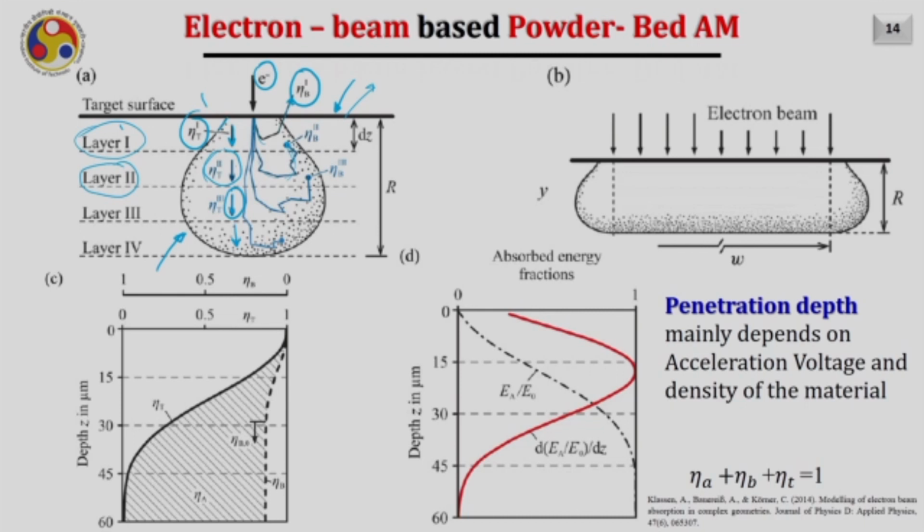Here you can see the top melted zone is not of much width. This is because many electrons got backscattered here. But further, when the transmission electrons are going further, the backscatter electrons are getting absorbed, and that is why in region 2 and 3 the width is quite high. Further, in the fourth region the available electrons are now less, and of course the width of the molten zone will further keep on reducing in this zone.